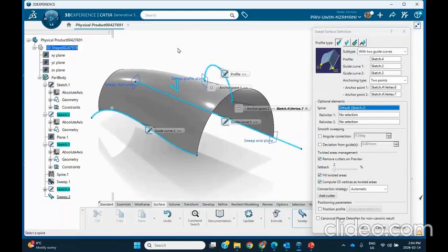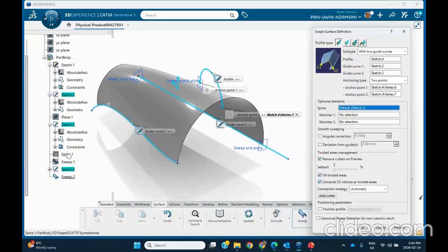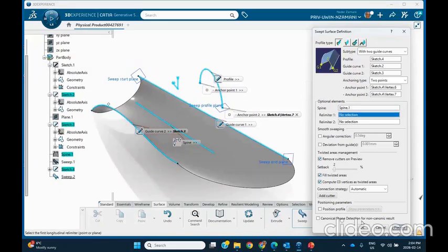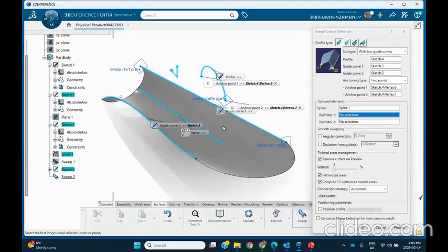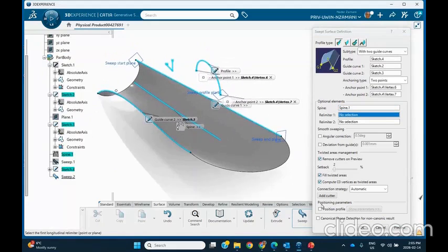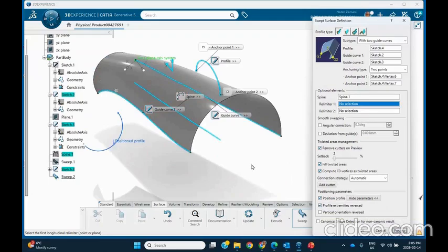Now this is using sketch 2 as the spine. Let's say that I wanted to use the spine that I calculated up here, the actual spine. I don't have to do it again because you're going to get the same thing. Remember this thing? Preview. Hallelujah. Now, sometimes the direction of these surfaces may not be what you want. So you go here, you set position profile, and you fool around with these to flip the direction. So for example, if I do this, let's see what happens. There. So now we go.